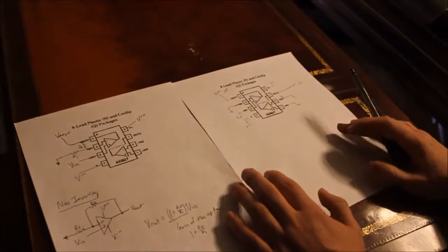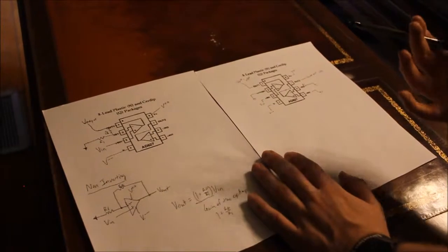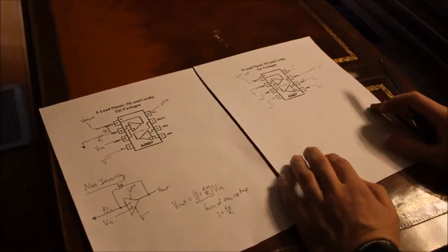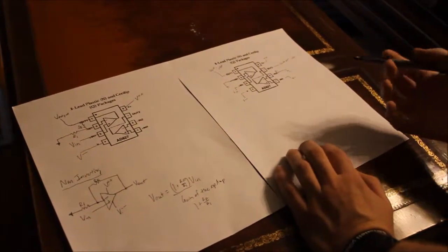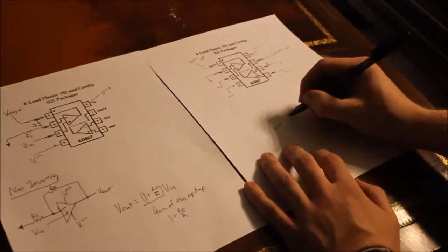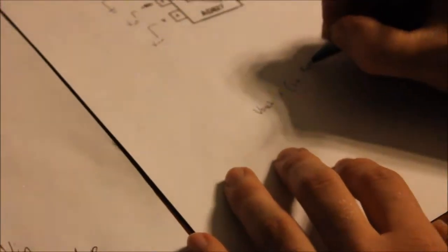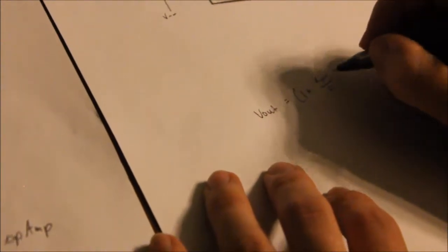Now, when we're also dealing with audio amplifiers, we want to amplify the sound, we want to make it louder, and to do that we need a volume control. One of the neat things we have to do that is a potentiometer, which we can use in this equation right here of our V out equals 1 plus, and we're going to change this RF to become R pot, which is the R potentiometer, over the Ri, all times the V input.